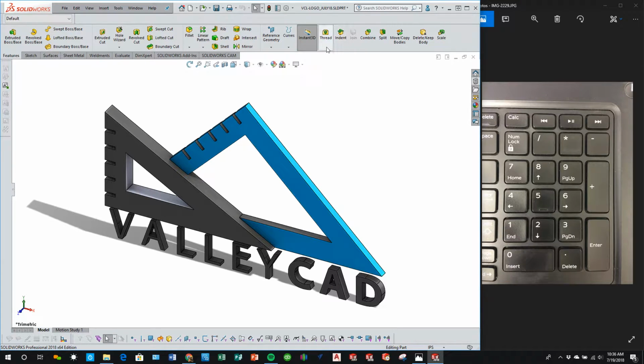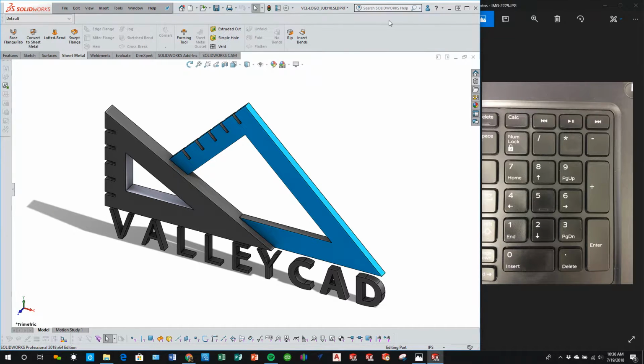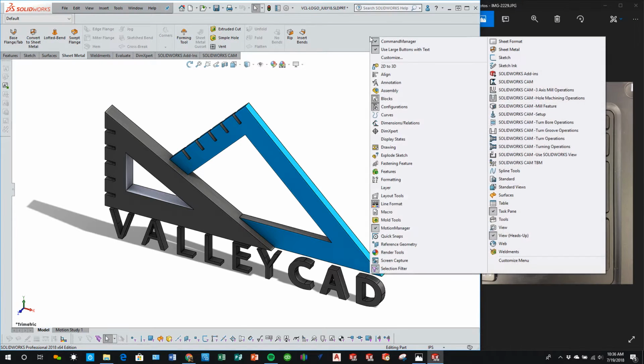What I like to do is come up to my command ribbon here and, anywhere in the gray, just right click. You could be under any of these command tabs. When SOLIDWORKS 2016 came out, they did something that really made me happy. Prior to 2016, whenever you right-clicked here, you'll see the word customize. This is where we want to go.